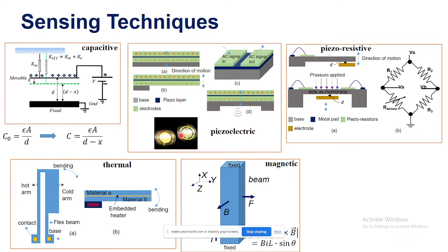Second example: we have already seen piezoelectric crystals. We can see them in the market, and they are widely used in several applications. Here we see a quartz. The structure of this quartz is very simple. It is basically two electrodes supported by a base at the bottom. This is the base, the green parts are the electrodes, and in between those electrodes there is a very thin layer of piezoelectric material. Based on the piezoelectric material, its type, its property, its geometry and its structure, the performance of this transducer will vary.